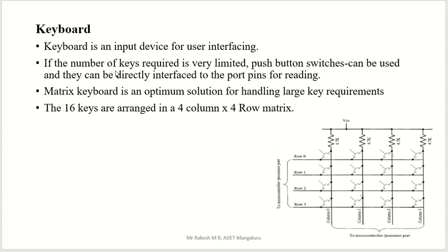Another input output device we can call the keyboard. The keyboard is an input device. We are giving input to the system by using the keyboard. If the number of keys required is very limited, push button switches can be used and they can be directly interfaced with the port pin for reading. We can use push button switches to build a keyboard also, the push button switches we saw in the previous slide.